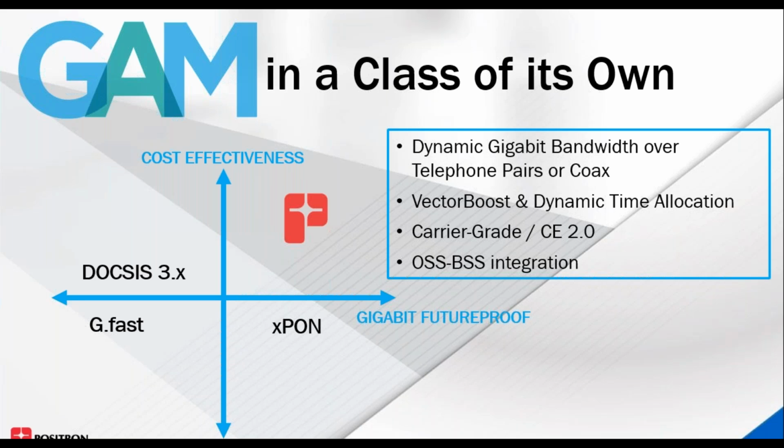A GAM can handle a lot more traffic, easily 10 gigabits per second that you can allocate across your users. So when you need to push more to the users, just crank up the uplink, the access into the building. The rest is already ready to handle that. As covered earlier, the dynamic bandwidth allocation is critical to match the demands and allows a lot more upstream than alternative technologies.